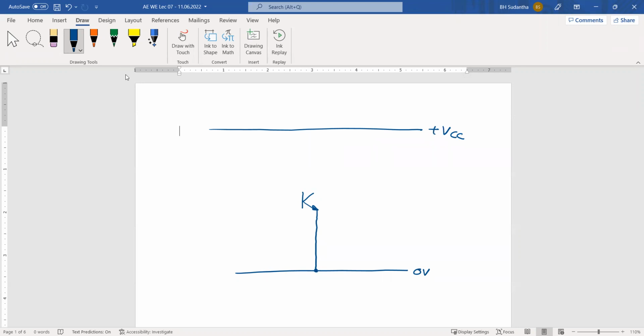To arrange all these things, to provide the proper voltages and currents for the conditions of the transistor, we have to arrange certain things. Arranging all these things means that we have to put certain components there to meet those conditions. First, we have to forward bias the base-to-emitter junction and reverse bias the base-to-collector junction. Those are the two things we have to do.